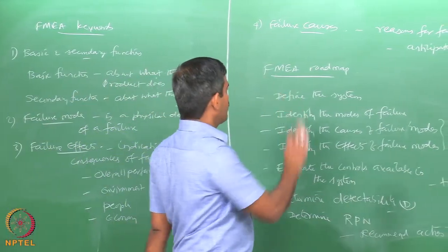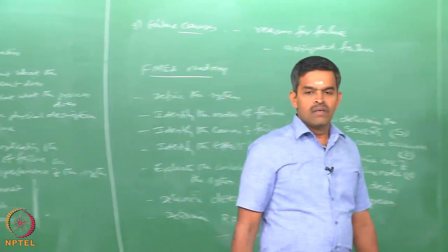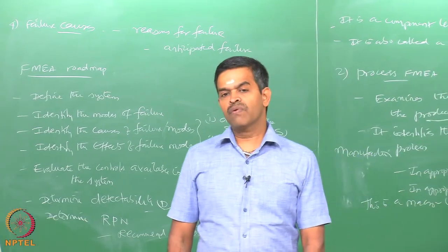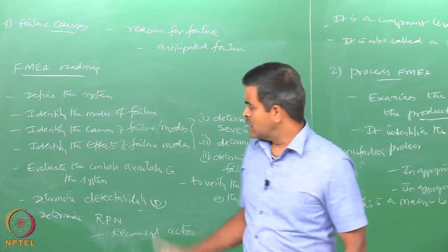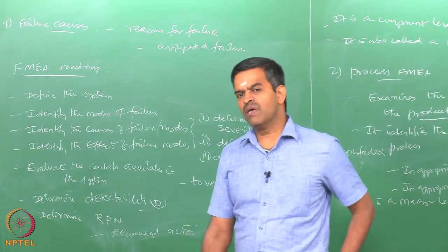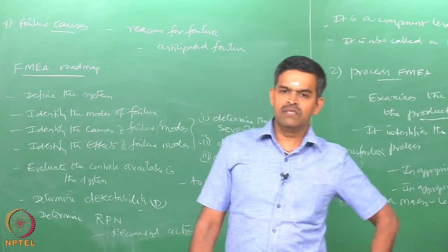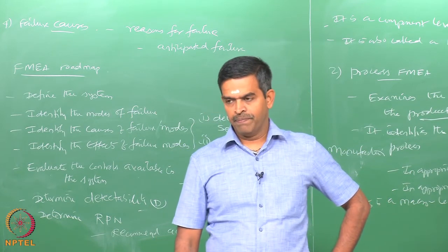So, that is going to be the FMEA roadmap, which is generally applied to any system, so that qualitative and quantitative aspects of risk analysis or hazard identification are covered in one shot using this, which is a very powerful and very common tool, in fact a mandatory tool for all electromechanical systems in the product development or in product improvement.